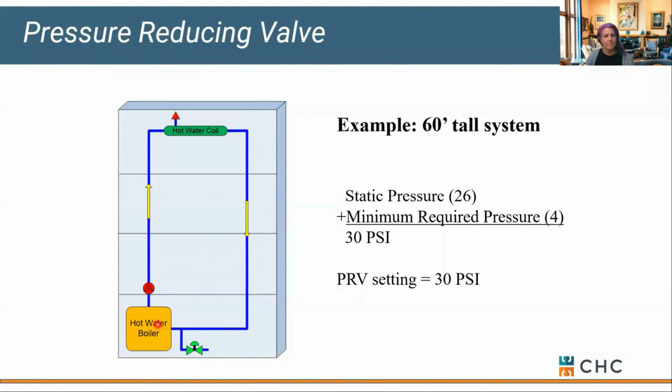Most boilers are good for 160 pounds of pressure. Most pumps are good to 175. Most expansion tanks are only rated for 125, as well as air separators. So if you're in a high-rise building, that's why most of the equipment sits up in the penthouse or upper floors, to alleviate that high pressure you'll see in the basement. But yeah, really good question.